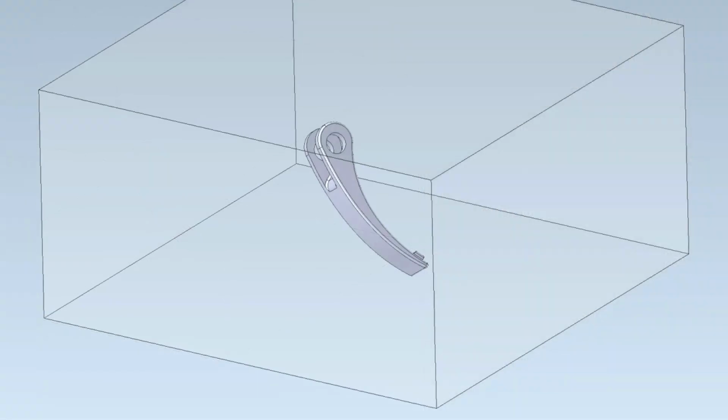Simple and angled supports with various perforation patterns and attachment methodologies are easily created with the aid of CGM Modeler's new support operators. First, patterns for supports are created with CGM Modeler. In this example, only one pattern is created for all supports. However, numerous different patterns can be created depending on individual supports to aid in heat transfer and attachment after printing.